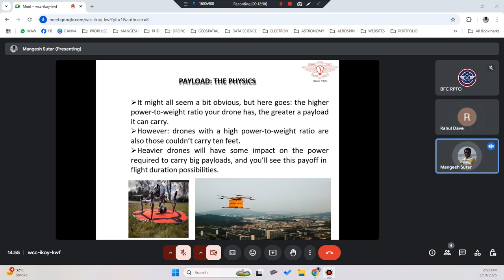Like if I go above 24, 25 kg, say I remove my payload tank of 10 liters and put in a tank of 16 liters, that means it will increase the weight. Increasing weight means I will definitely lose endurance. I may say, okay, I'll put in another battery. Right now I'm using 21,000 mAh; let me put in 30,000 mAh. But what about motor capacity? Correct. Because though it is 50 kg, I cannot use beyond 50% of the actual thrust, 25 kg. I cannot go beyond that.